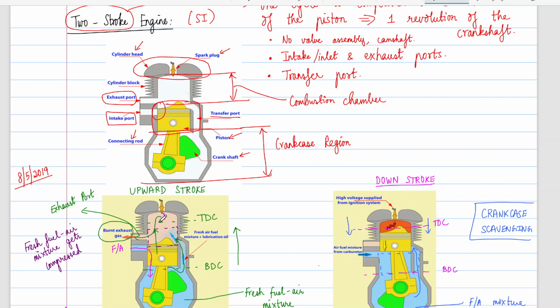Take that as the energy which is being consumed, and on the other hand, I will connect the output of the gearbox to a dynamometer which has torque measurement capabilities. So I will measure output torque, right? And this output torque I can then use to see how much power I am getting out of it.